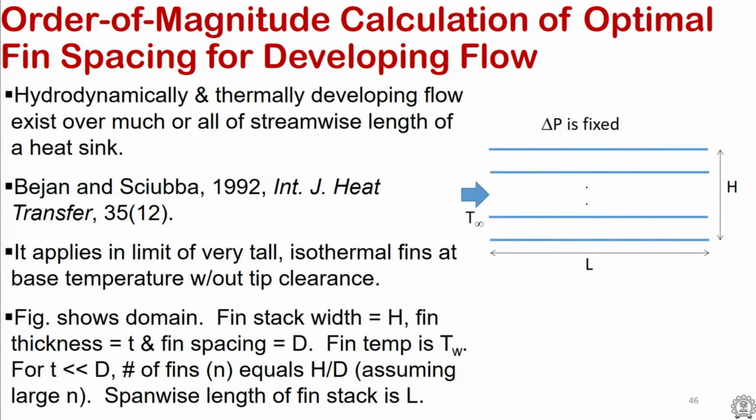is that there are these blue lines of the fins and the volume is fixed. This is a top view. The total width of the heat sink is kept at H. The flow comes in at some T inlet or T infinity and flows along the length of the parallel plate of L, and there is some certain depth as well that is not discussed here. And the flow is considered to be hydrodynamically as well as thermally developing. So it doesn't restrict itself to some developing flows.